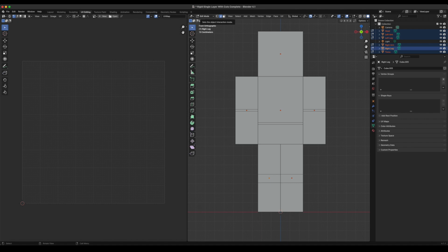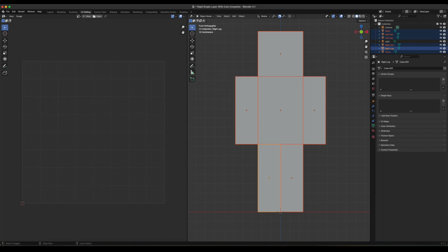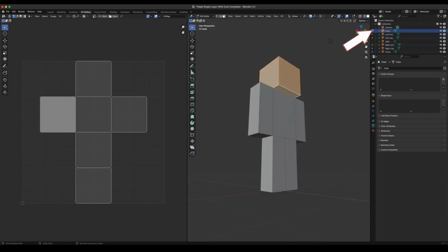If your view for both workspaces looks different, perhaps more like this, check to ensure you're in the correct mode. A lot of the UV editor's functions disappear when the main workspace is placed in object mode. We'll use object mode to select the object we'll be texture mapping, and then edit mode to directly select the faces being mapped, and to make adjustments in the UV editor. With the object selected and back in edit mode, we ensure we have face selection.